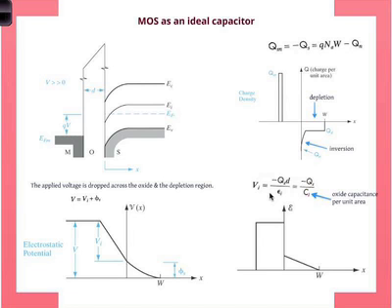So we can treat the metal oxide semiconductor as a capacitor. Like I said, looking at it, you rotate it 90 degrees from the previous picture. So we have a gate here, oxide here, semiconductor here. The signal comes here. Okay? So the impedance seen by the signal is whatever capacitance is here. So it's important to know that. So remember, when you have a circuit, the gate will be the input to some small signal. So you need to know what impedance that signal will see in order to design the circuit. Okay, so that's the goal here. Keep that picture in mind. And later on, we'll put this into a circuit so you have some experience.